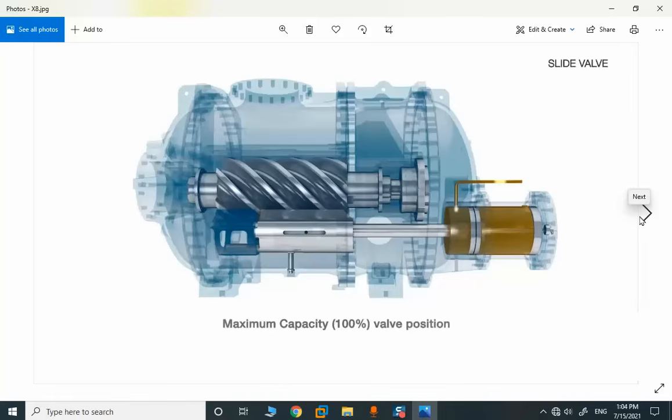So consider we have these binary actuators, and we want to use them in a PID application. Normally we have seen that we have analog input and analog output. In this PID we have analog input, but the outputs to operate these actuators are binary signals. So we have this algorithm, and we implemented it in the calculation block within the DeltaV software package.